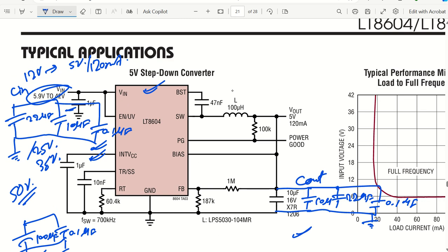Now coming back to the inductor design. For the inductor, the L value was there, one formula was there. So use that to get this particular value. You have to make sure the current rating of the selected inductor is more than around twice or thrice of this particular current. By default, you can just close your eyes and choose around 1 ampere or 2 amperes of rating. That will always be sufficient, but it may be a little costly, so you can go ahead with a 0.7 ampere rating also to reduce the cost of your inductor.